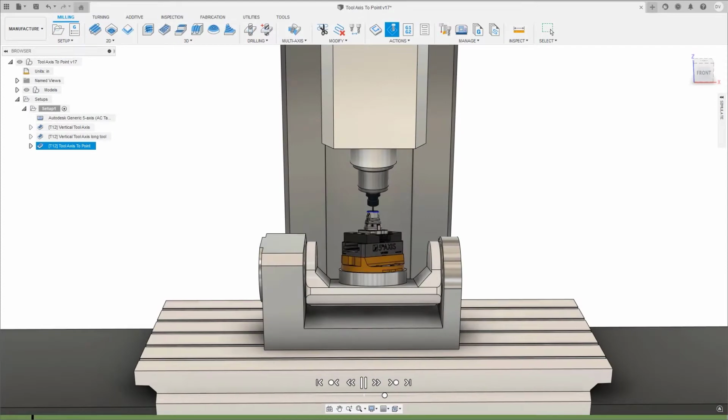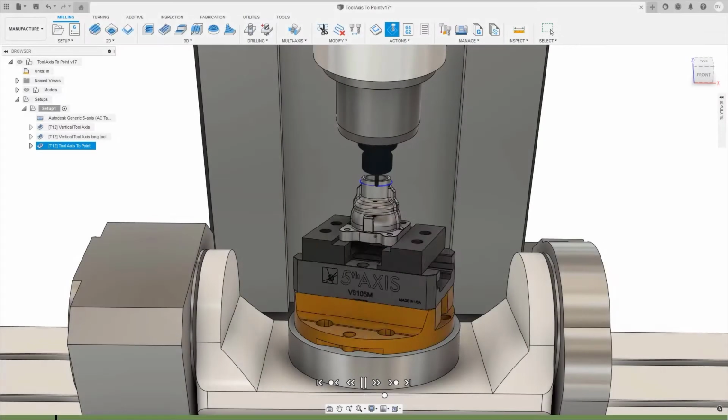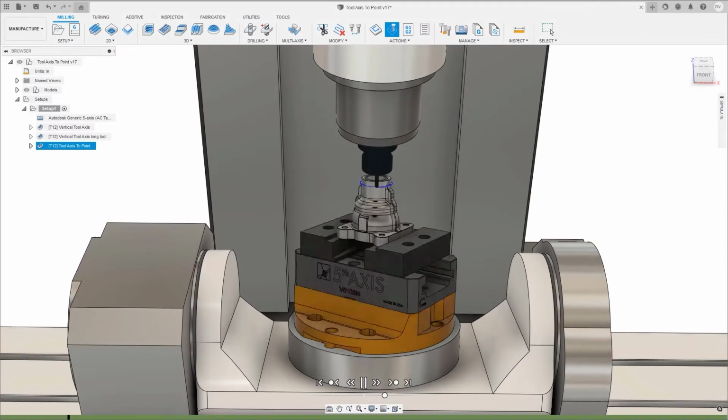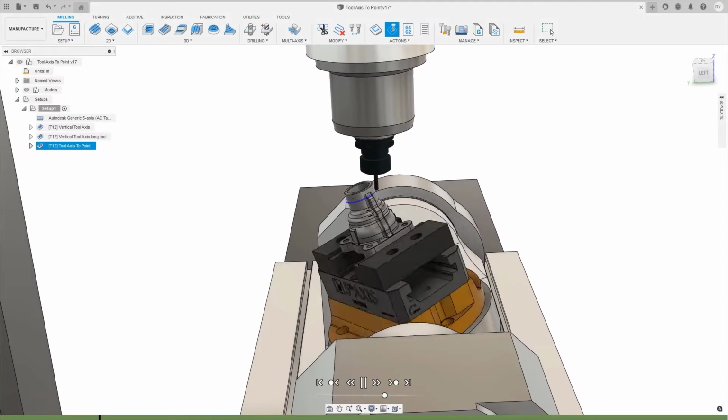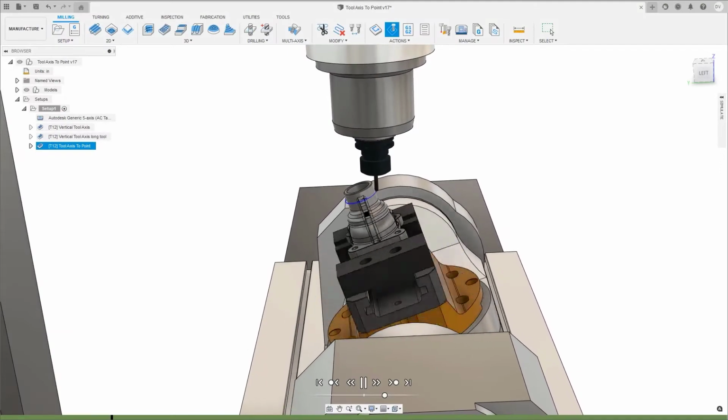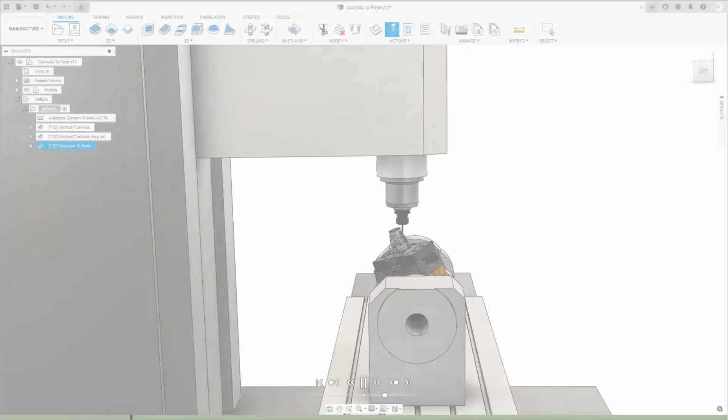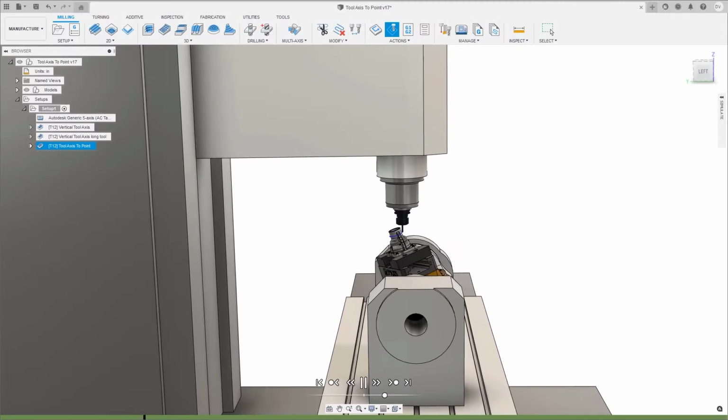Multiple setups, poor cutting conditions, and interference with a machine or tool. These are all issues that can occur during part manufacturing. The introduction of a 5-axis machine tool to your manufacturing process, which adds an additional 2 rotary axes to control the tool axis during the machining process, can minimize these issues.